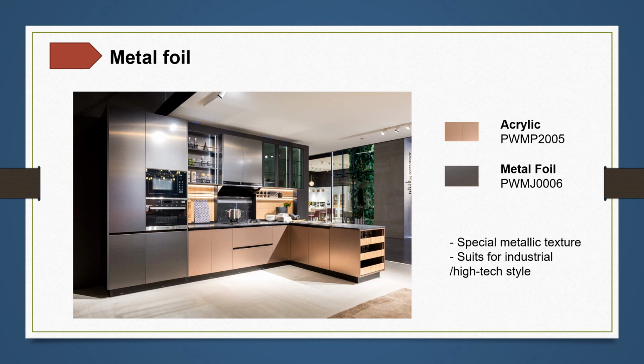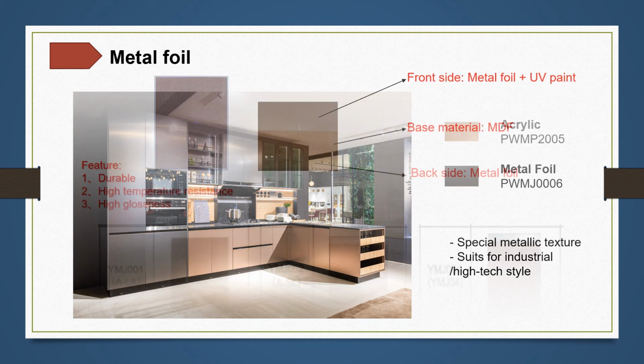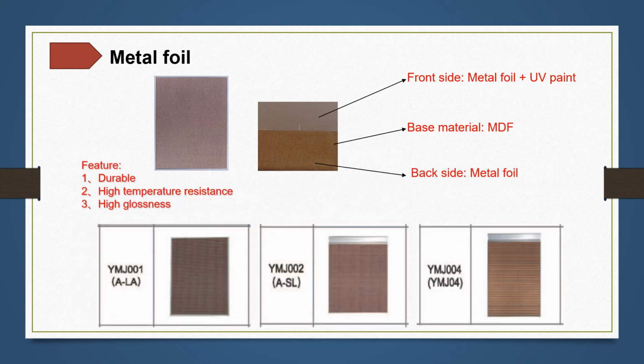For wood frame glass door, the craft process is to cut holes on all kinds of finish and put the glass in. The two typical glass doors matching with flat panels are YMB001 and YMB006. The first one, YMB001, matches with paints and thermoplastic finish without edge sealing. The surface material will cover the four edges of the hole. On the contrary, YMB006 stands for finish with edge bandings, and the factory will also use the edge bands to seal the four edges of the glass hole.